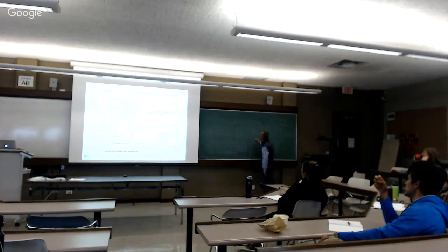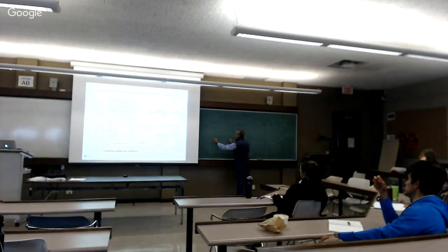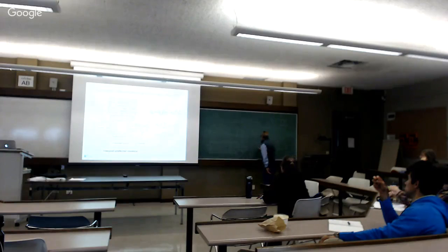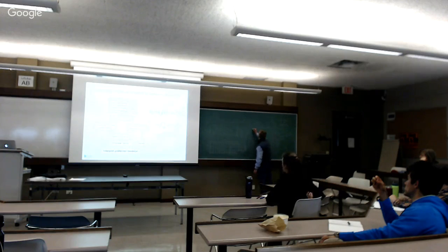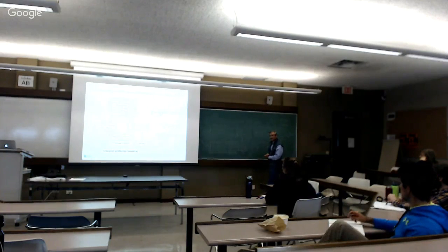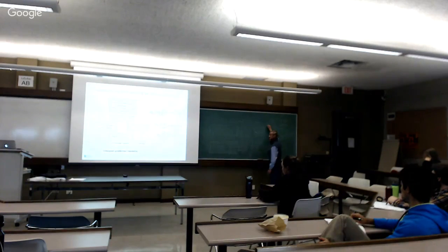And then we get some data that we've measured up here, all the values of the pseudosection, different n spacings, different locations on here, so that the data, you know, might be D1 to Dn, so maybe n is 1,000 data or something like that. The relationship between these is a linear relationship. J eta is equal to D. So D is our data, eta is our big chargeability model, and J is a matrix.